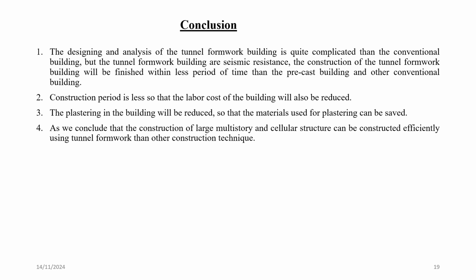So, in conclusion, we learned that the designing and analysis of the tunnel formwork building is quite complicated than the conventional building. But the tunnel formwork buildings are seismic resistance, and the construction of tunnel formwork buildings will be finished within less period of time than the precast building and other conventional buildings.